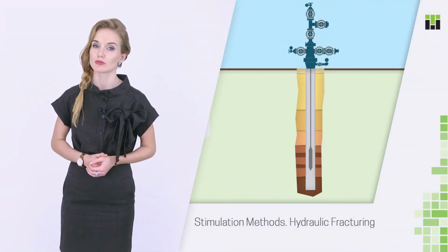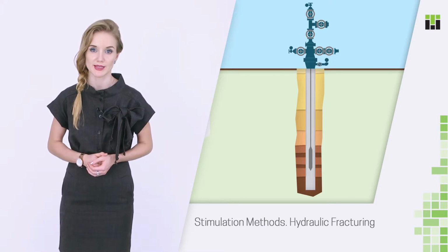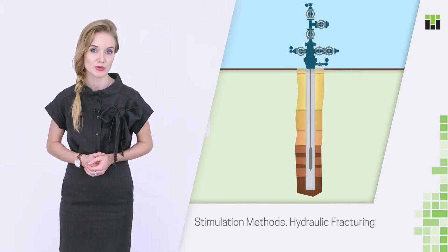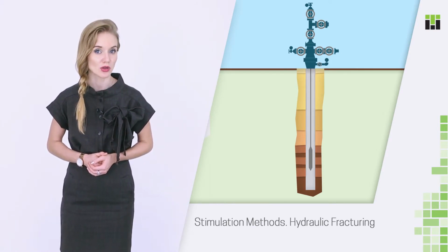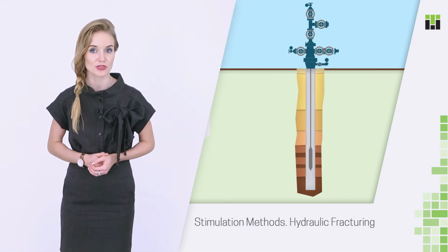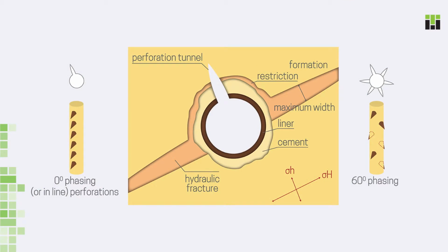This information can be obtained from various well logging data, and we already know what well logging is. I should mention that for frac design purposes, we need logs not only from productive intervals, but from the adjacent formations as well.